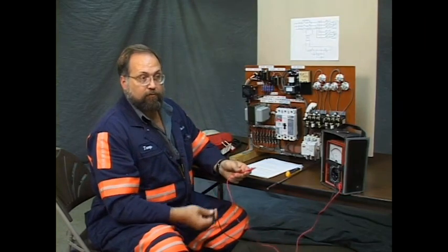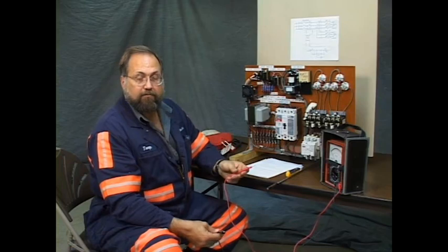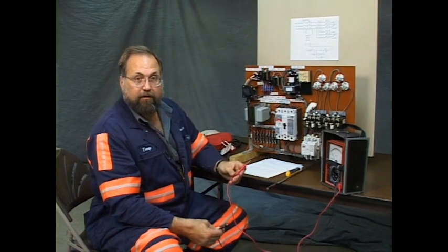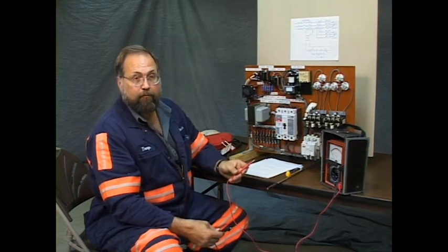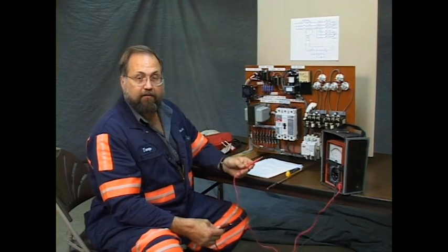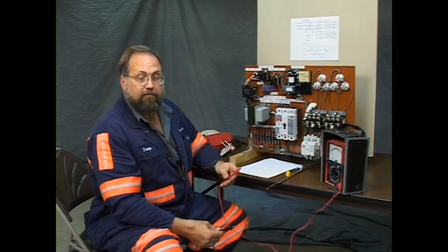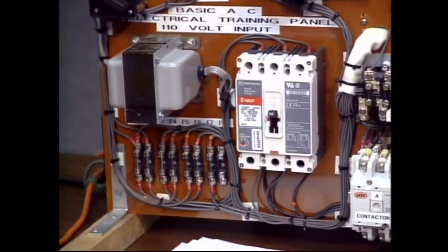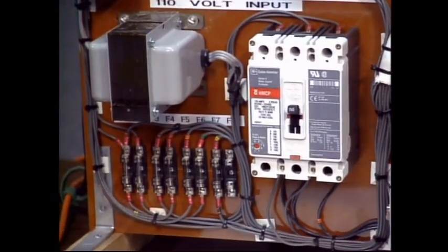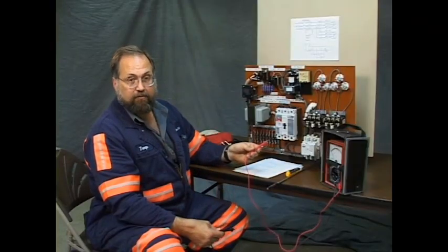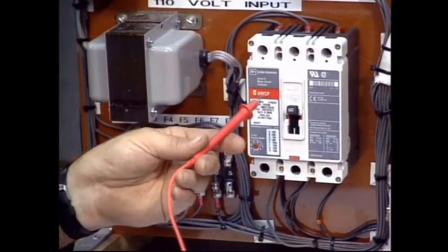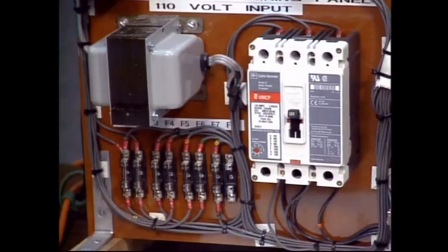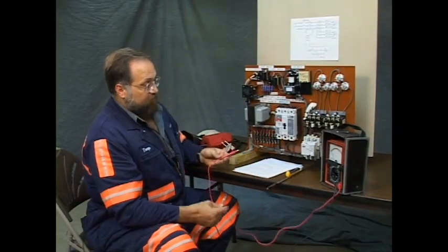Now, that handle, it's in the on position, it's in the closed position. You'd think for sure the circuit breaker is closed and doing as it should, but as a matter of fact, on mining machinery, a circuit breaker failure is not at all uncommon. Before you can say with any certainty that the breaker is either open or closed, you would have to use an instrument to read it because the contacts are not visible. That is why a circuit breaker is not considered to be an adequate visible disconnect, because the contacts are not visible. You can't visibly determine that these contacts are either made or not made or open. But we've determined that this one is good with this instrument.